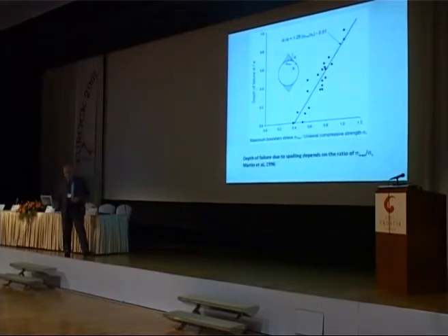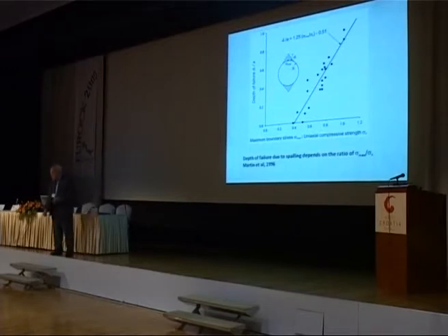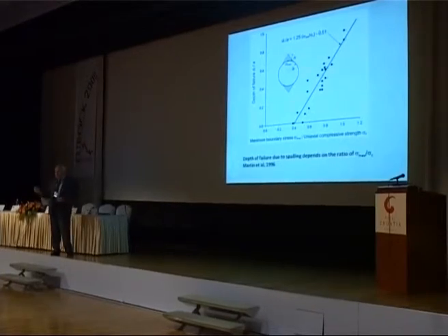What we do know from a practical point of view is that the depth of the spall is very closely correlated with, again, the maximum boundary stress over the uniaxial strength. So that from observations all over the world, and these are observations from mines and tunnels all over the world, this again is a fairly tightly defined process.